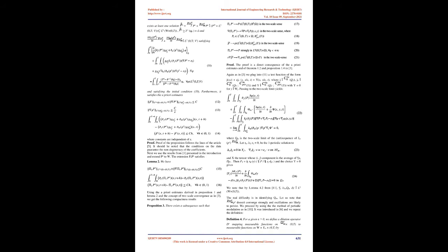Hence, in order to have an effective equation for the velocity and the pressure, we study the homogenization of the Richards equation. The Richards equation in the dual porosity case reads as follows, (7), where δ is a small positive number, p^ε are the unknown, scaled, pressures, θ is the water content and K is the hydraulic conductivity. Let us note that we have two functions θ and K.